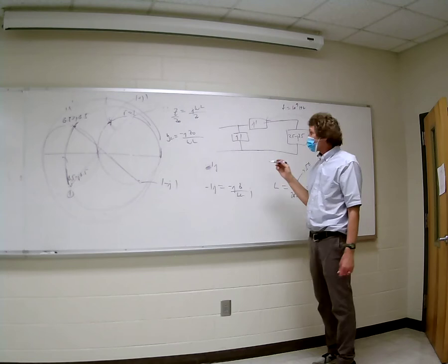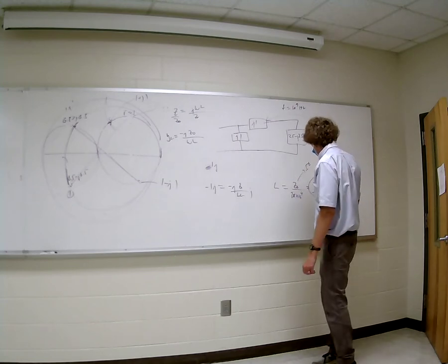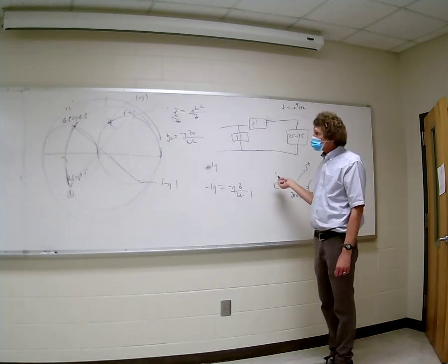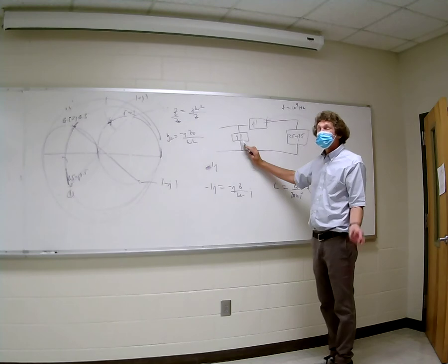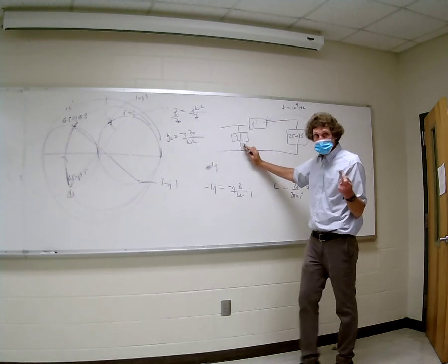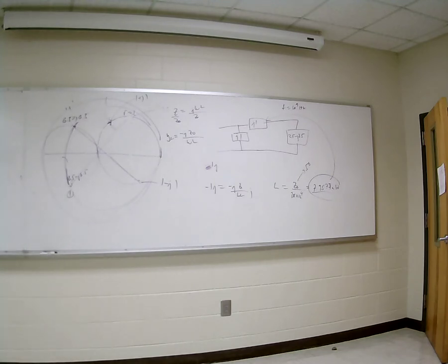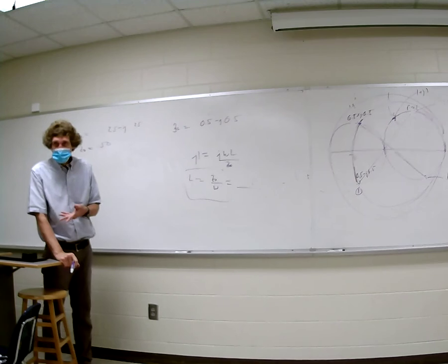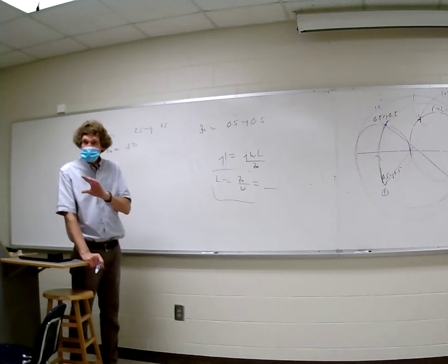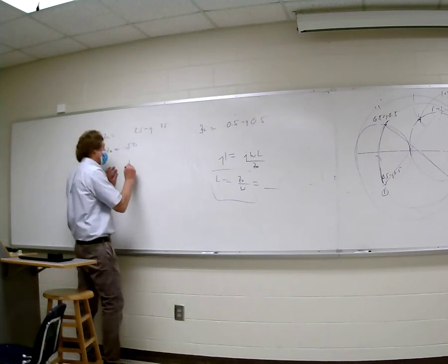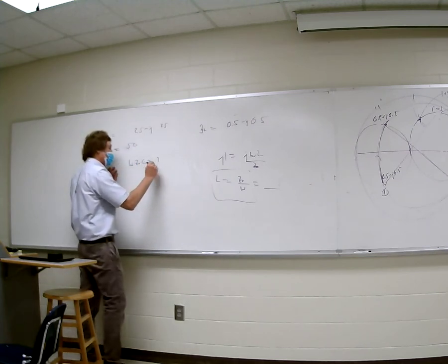And that's it. So we got the value of the inductance, which is 7.9577 nanohenries. And if that's the normalized admittance, what's the value of the capacitor? I got 3.18 picofarads. Yeah, we know that the normalized capacitive reactance is 1 over J omega C. Normalized, it's 1 over J omega C Z naught. Everything's downstairs. 1 over that is the normalized admittance, which is J omega Z naught C, and it has to be equal to 1. So we have omega Z naught C equal to 1.